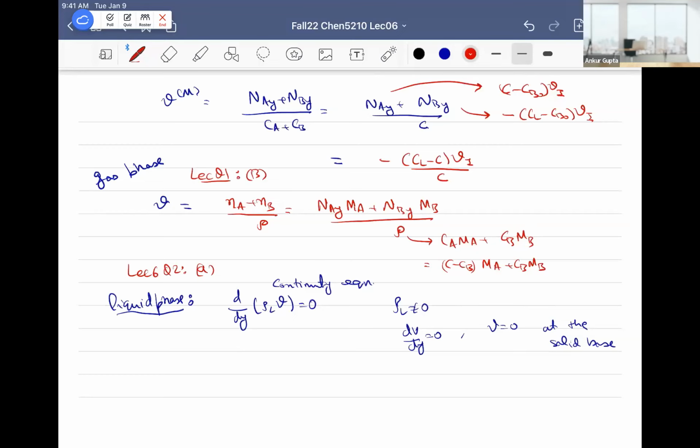But if I say M is equal to MD, then you can see, I'll get some density, right? Then the mass average velocity, I'll still get some value which is not necessarily going to be 0. So I can still substitute M equal to MD and get a non-zero answer, right? So it doesn't necessarily imply that I need a difference in molecular weights. Difference in molecular weights might just make my density constant. That's all. That doesn't cancel out the fluxes.